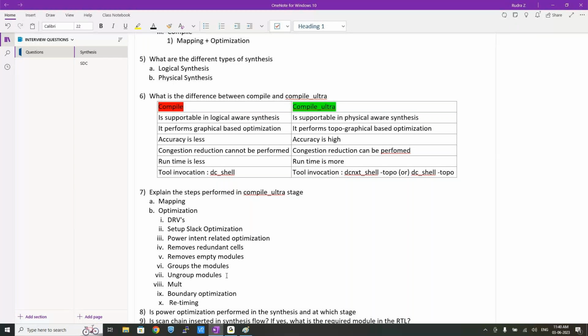Without changing the functionality, the tool will try to reduce that count variation. Sometimes the same definition, or the same functionality, is found in parallel. It will try to remove that redundant case, where it would increase the fan out. That kind of possible case will come.